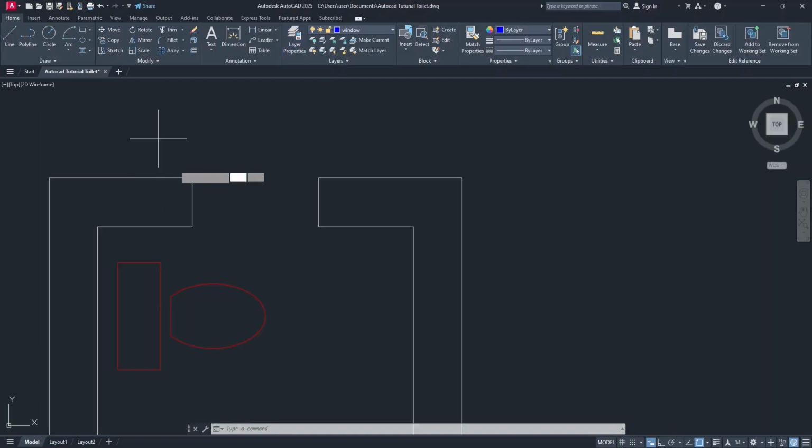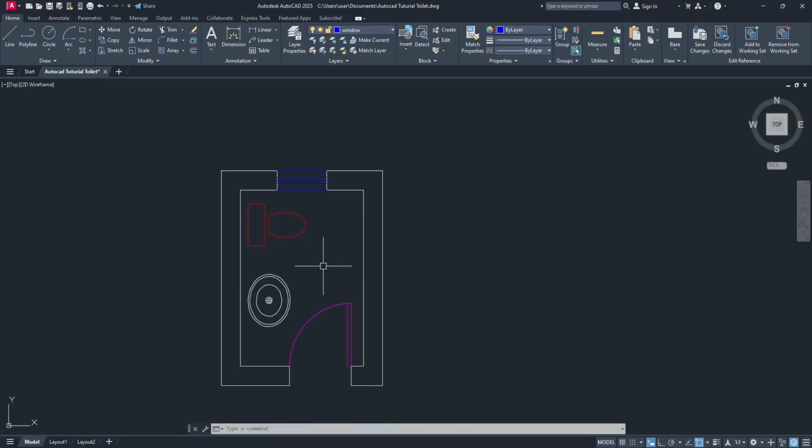Now select a line, I will click here and then click on this midpoint, and then I will press the enter key. Now I will select this offset and I will select true. I will select this line, select this endpoint, click and select this endpoint. Click, just click somewhere close. It's just a window, we don't care. Press the escape key, zoom back a little, and that's pretty much it.